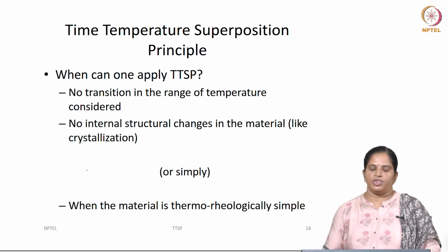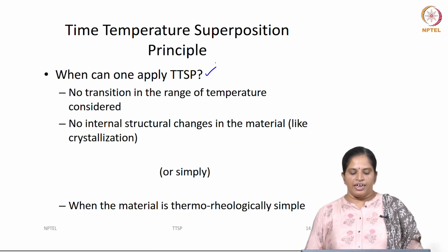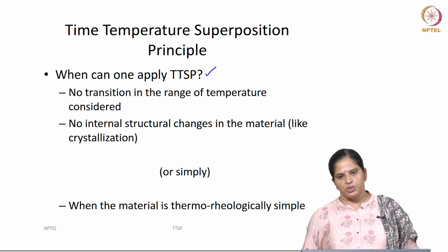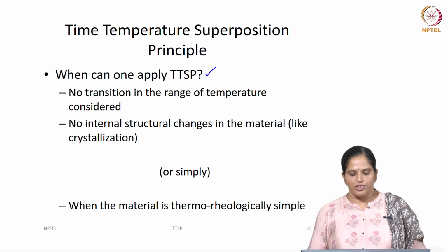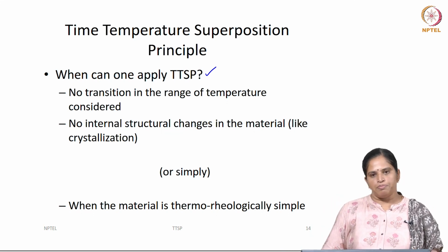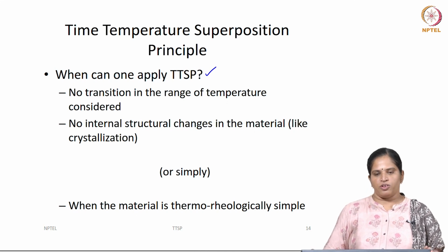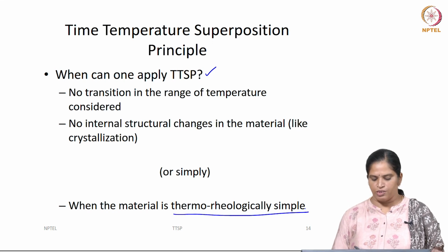So, now the next question is, we have defined what the time temperature superposition principle is. Can we apply the time temperature superposition principle for all cases? The answer is no. As I said, we can apply the time temperature superposition principle when the material exhibits a thermorheologically simple response. So, when the material is thermorheologically simple.